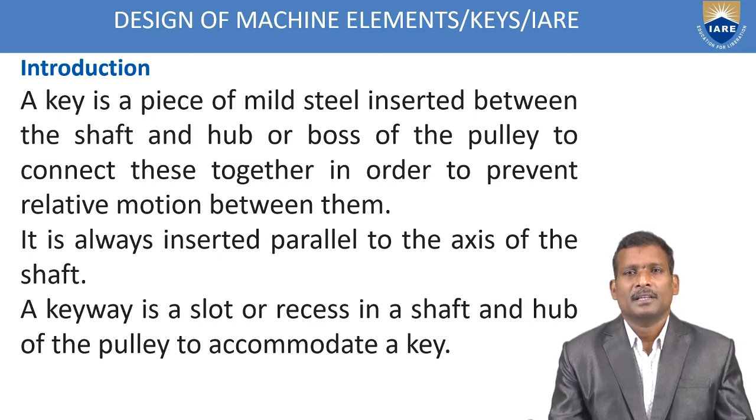And the keyway is a slot or recess in a shaft and a hub of the pulley to accommodate a key. So in the keys topic, two terms are important: one is key, another one is keyway. The key, as we have already discussed, is a mild steel piece. And the keyway is a slot made on the shaft and on the hub.